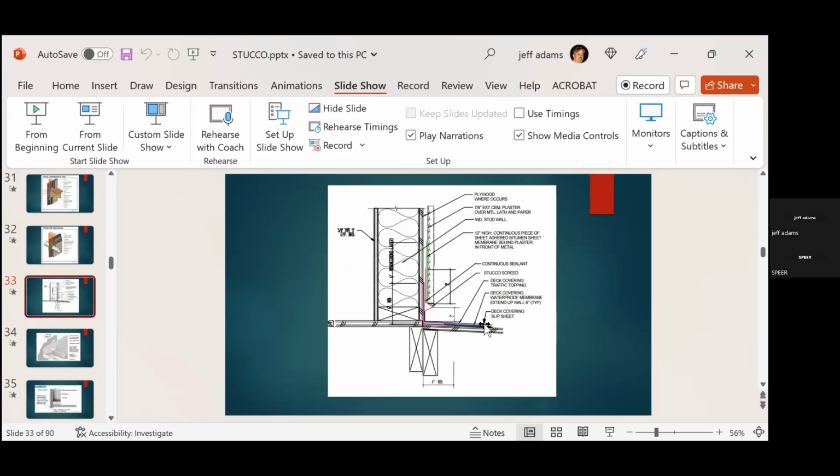This is a roof detail that I plagiarized that I love. Because it gives you your base flashing here for your roof, okay? And they're just ending this with a foundation weep screed, okay? Great way to do it, coming up off the roof 2 inches. It's being secured up here. We're not punching any additional holes in our flashing like you would with a plaster stop or a casing bead. And so it's just creating everything we need this to do. The water comes down, drips off the drip edge portion of this. This is where the water comes off, is down on the very bottom aspect. That's a 45-degree angle that creates a drip edge.